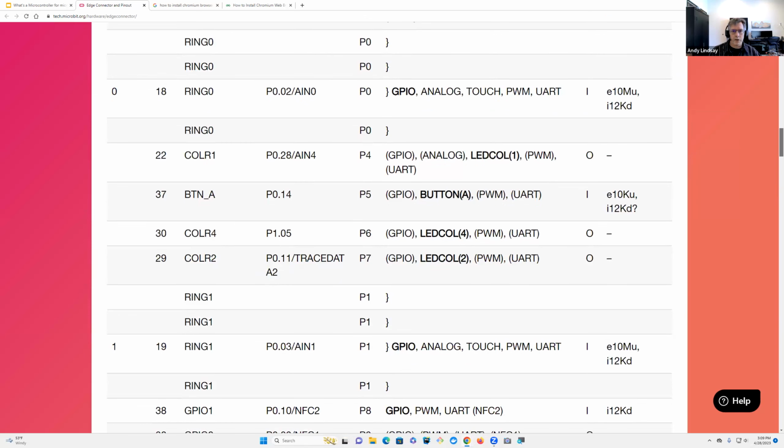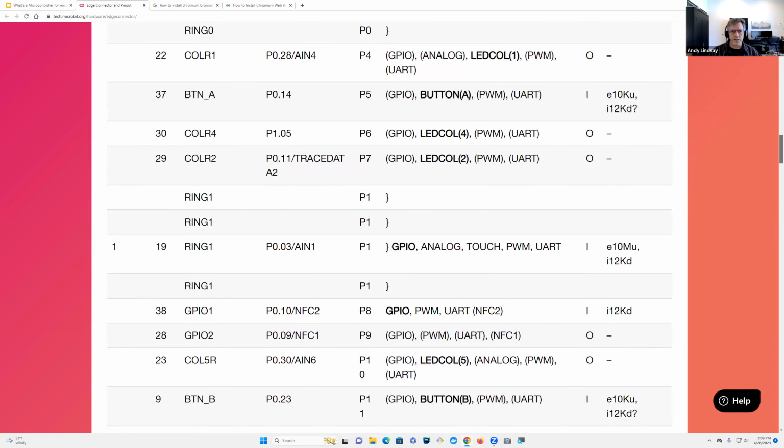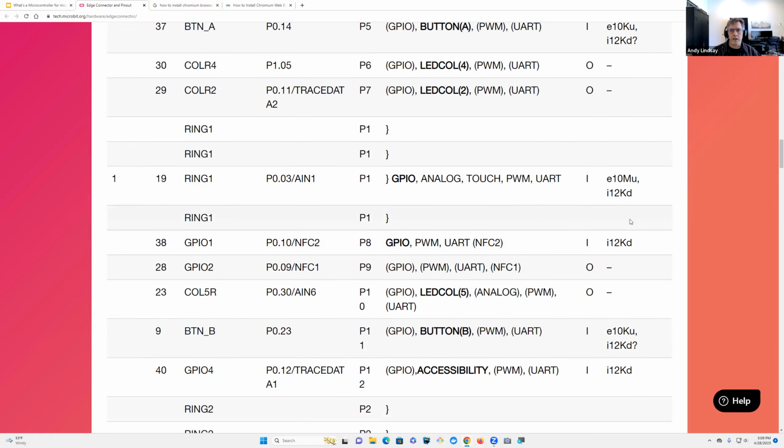And you may have noticed in some of the scripts where it says set_pull, and then the pin number, no pull. And the reason for that is because there are some pins, like, let's take a look at P1 here. By default, P1 starts up with a 12K resistor connected to ground. So that joins the party of any circuit that you might connect to that. And so you'd have to know, if you didn't want this 12K resistor to interact with the circuit, to tell it no pull resistor of any kind.